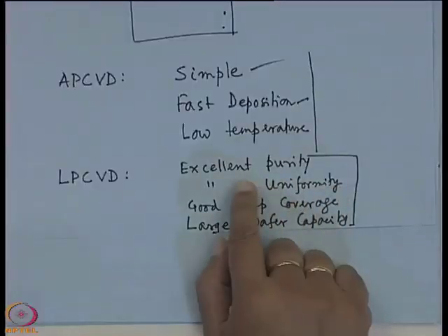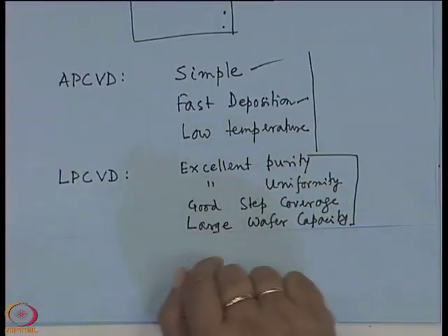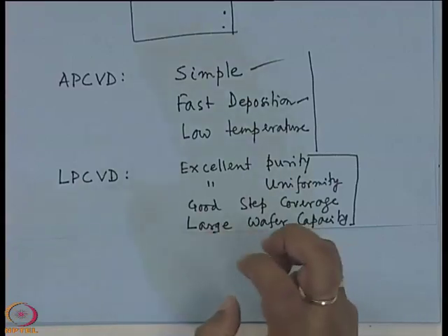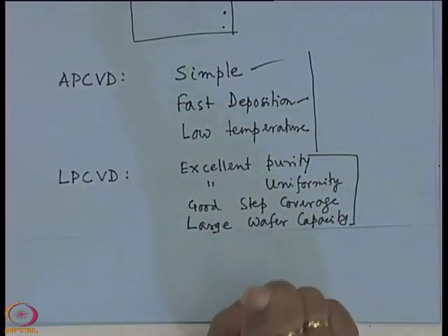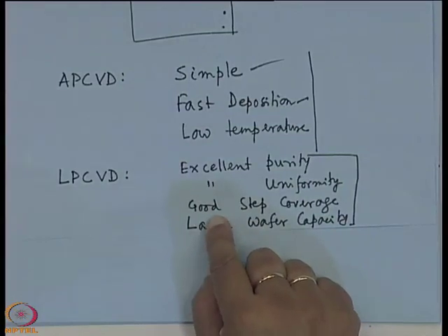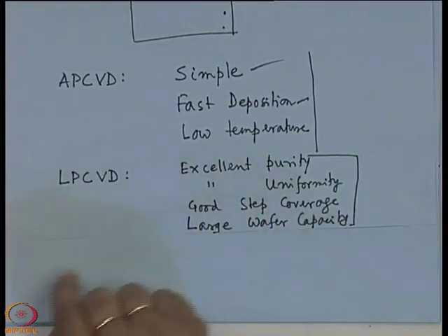In LPCVD we have written that the purity is excellent. Why is the purity excellent? Because the reactor chamber is evacuated. If you evacuate something, there is no air inside. If there is no air inside, the purity level will be higher. So, there is some advantage. And another important aspect is that it will have good step coverage.